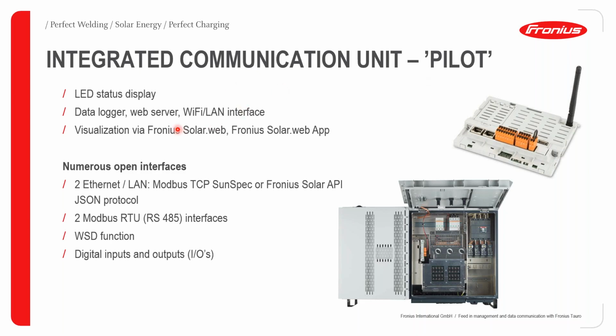What is the pilot card? Well, the pilot card contains your data logger, your web server, and your Wi-Fi and LAN interface all together. This will provide the basis for visualization on Fronius Solar.web and also for visualization on the Fronius Solar.web app. With our new Fronius Tauro inverters, we no longer have an LCD display. Instead, we now have an LED status display.